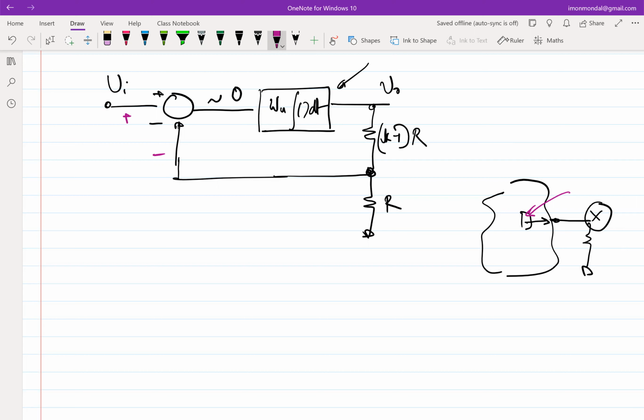But when things are in negative feedback, you have to think from the back, think from the opposite side. Essentially, you see that whatever it is driving is a forward path, and your feedback loop is more or less insensitive to the forward path. That's the whole idea of making a negative feedback loop. So the whole purpose of this integrator is to give you large gain. If the gain goes from maybe 1 million to 1.5 million, you will really not see too much of a difference at the output voltage. Even though one might argue that everything is in negative feedback, so everything affects everything, you have to identify which thing in your negative feedback loop affects the output more than the other.